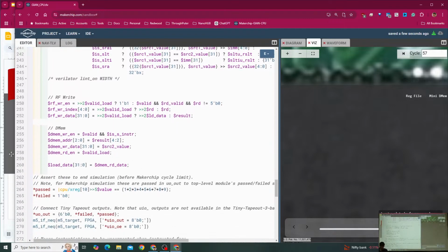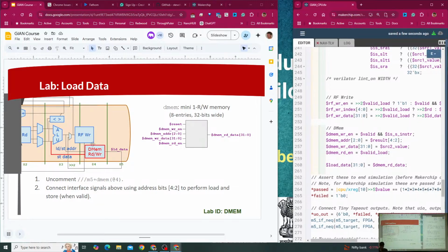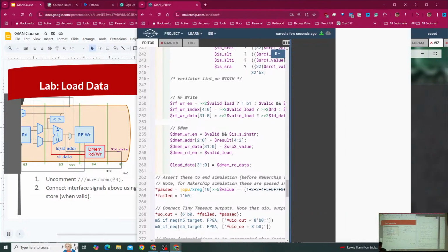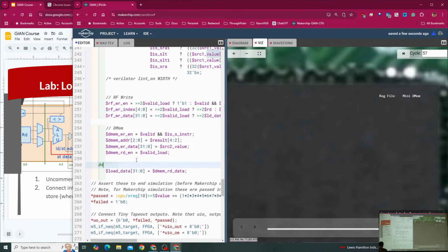So what I want to implement is this picture. The memory is in stage 4. All of my inputs are ready in stage 3. So assigning the inputs in stage 3 is fine. But my output from the memory is apparently not available in stage 3, which from this diagram makes sense. So let's move this to stage 4.